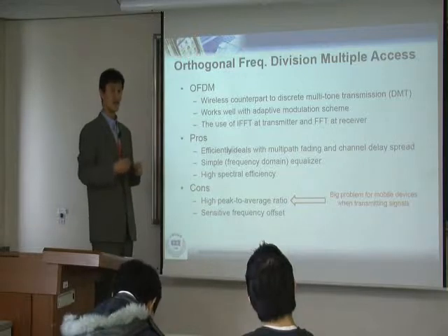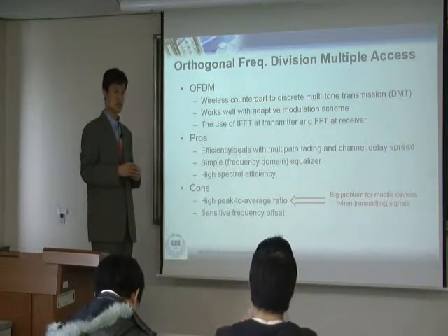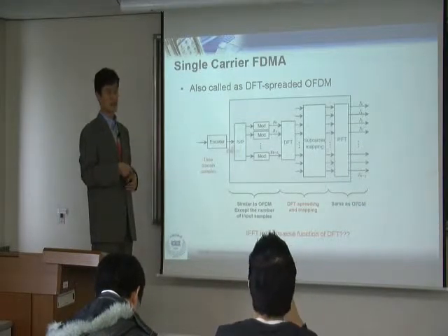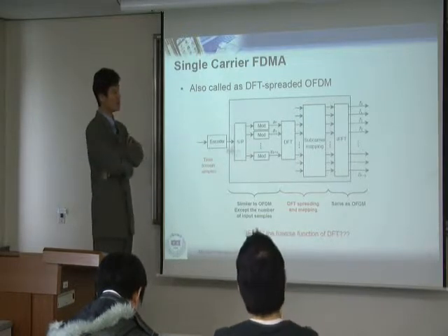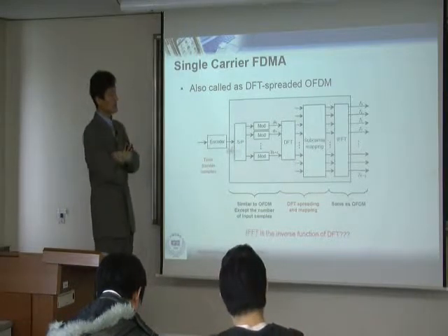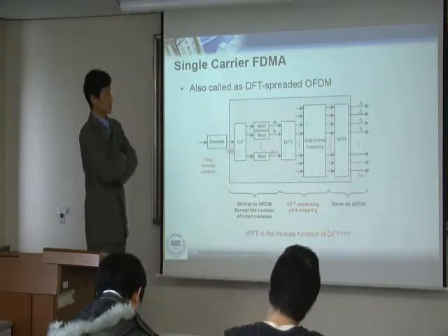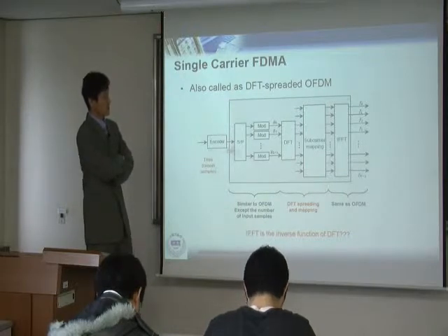So therefore, in LTE, the newer cellular standard based on OFDM, they use this technology, single carrier FDMA, instead of OFDM. In LTE, this is the technology for uplink. So this is a simple picture of single carrier FDMA.